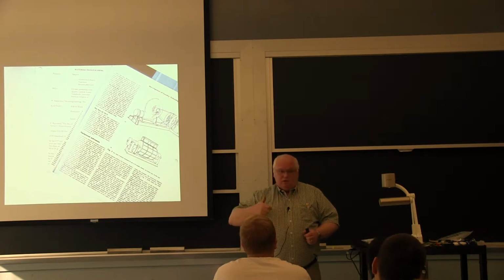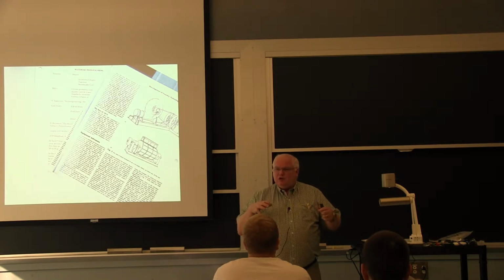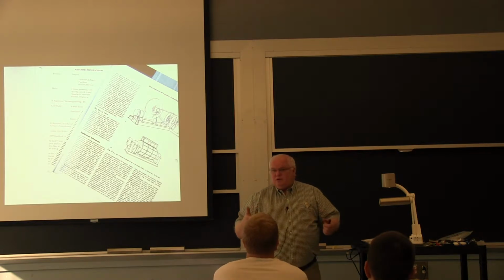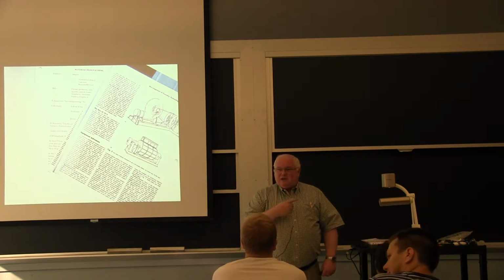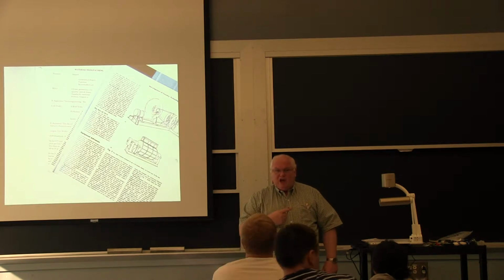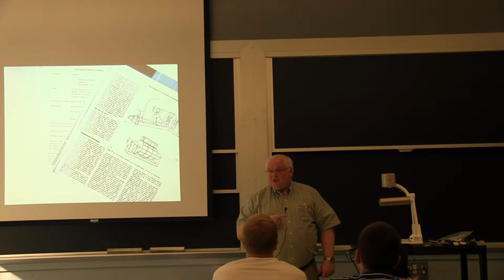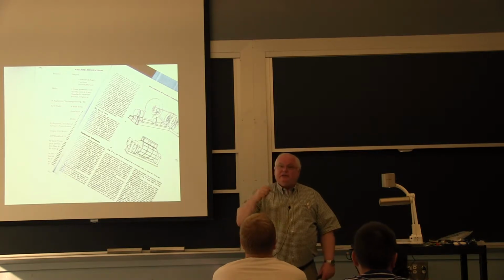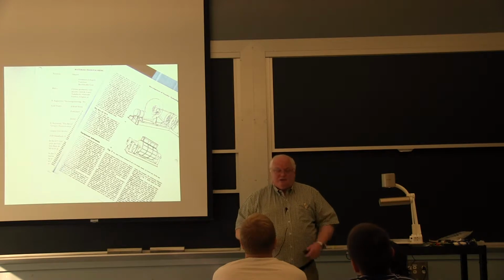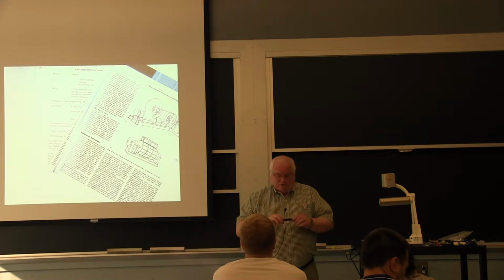Now, most of the coal that we burn in a power plant is what we call bituminous coal, which has not been cooked as long and it has a lot more volatiles in it, or even subbituminous coal, which is sometimes called lignite, and it's old plant fibers that have not been cooked very long. And you can buy that stuff out of Colorado or Wyoming at $5 a ton today. It costs you more to ship it out of Wyoming than it does to dig it out of Wyoming, so coal is pretty cheap there. In West Virginia, the better quality coal might cost $40 or $50 a ton.